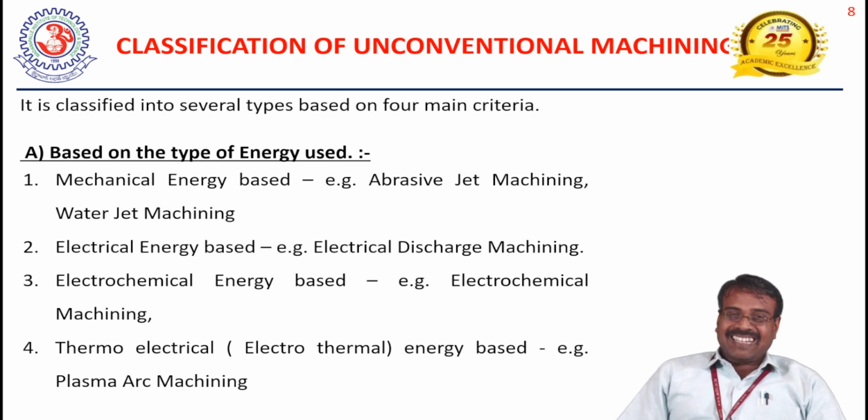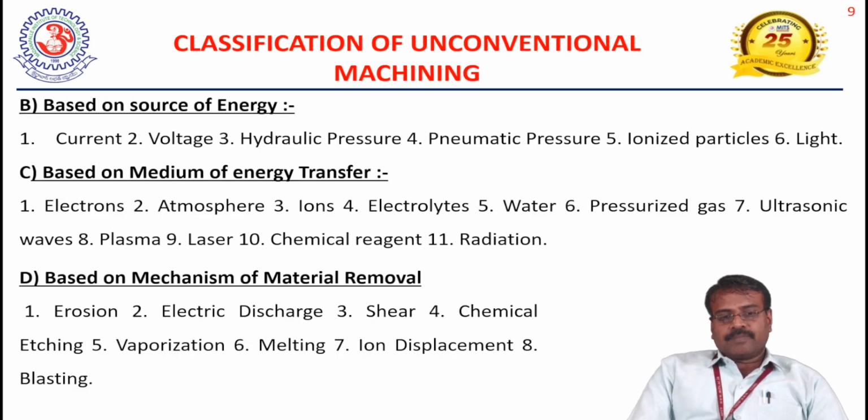Next one is electrical energy based. The example is EDM, where through a heavy electrical power supply we are removing the material. Then the third one, electrochemical energy based, is the ECM method. Then there is also plasma arc machining under electrical energy based. So like this, we can categorize.